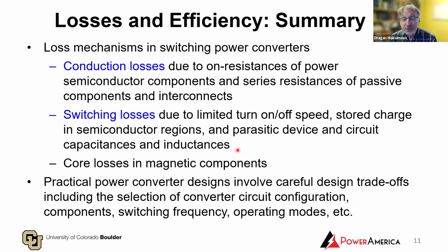There are also other losses that I haven't mentioned explicitly here, such as core losses in magnetic components, and series resistances in magnetic components also have dependence on the switching frequency because of uneven distribution of current through the windings. Practical power converter designs are complex.